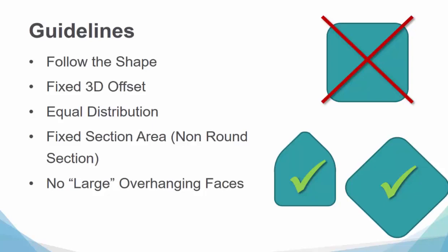So now I reach a point when I come to the very top, I have to go all the way across it with nothing but powder supporting it. And that can cause the water line to not come out to the shape you desired, right? So you see in the other options, the doghouse shape, or perhaps taking that square and rotating it more to a diamond shape so that you can slowly build up the sides as they come together to the top. Those are called overhanging faces, and that's one of the key things to understand when it comes to printing these water lines.